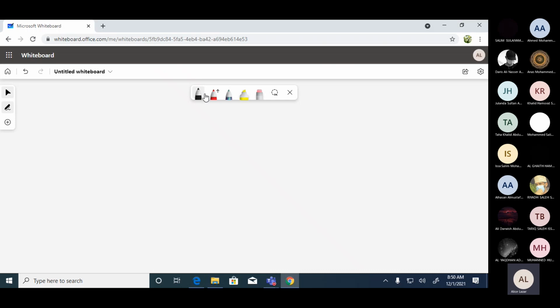So when I say on-off controller, you can also think of this as a controller which is having two positions. 100% is on, 0% is off. You can have completely on or completely closed. There is nothing in between.